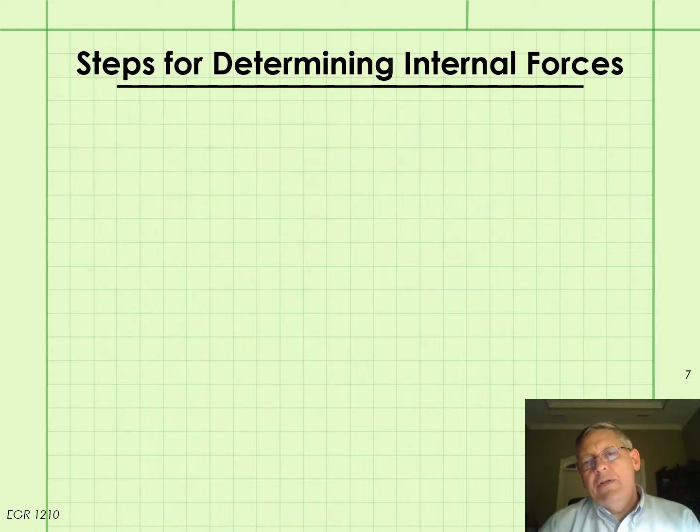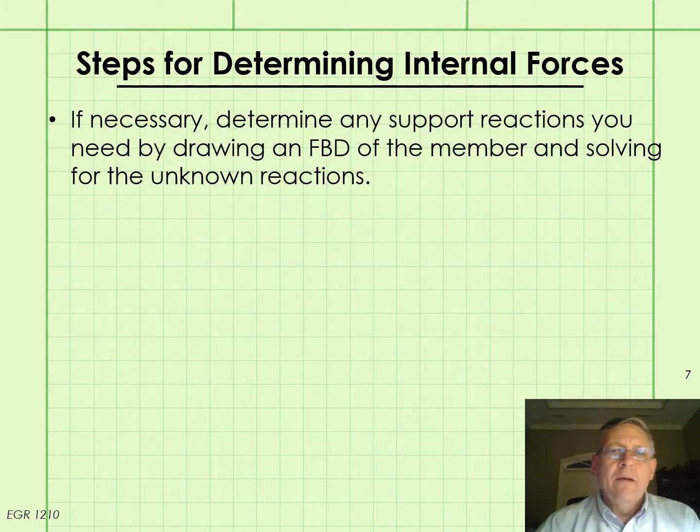Here are the steps for determining the internal forces in members. First, if necessary, determine any support reactions you need by drawing a free body diagram of the member and solving for the unknown reactions. This is nothing new. We've been doing this for several weeks now.